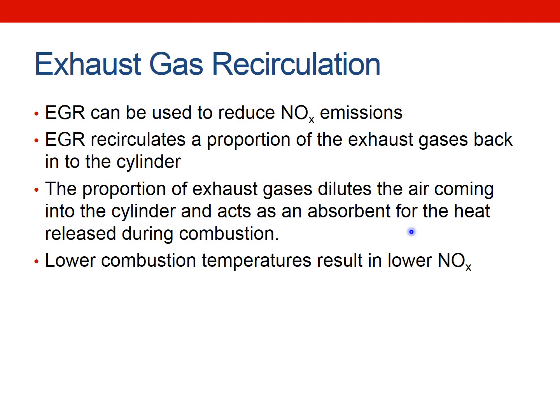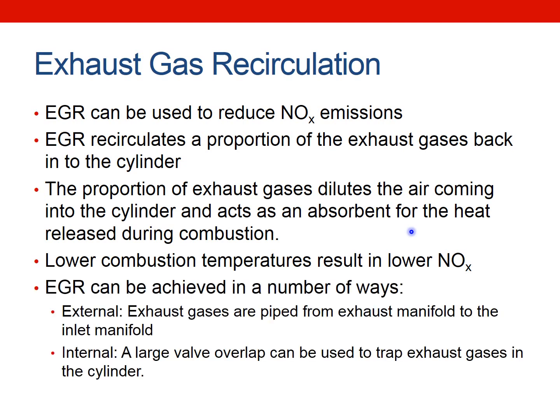And it's a lower temperature that gives lower NOx. And as I said, there's two ways it can be achieved: external, where the exhaust gases are piped from the exhaust manifold to the inlet, or internal, where there's large valve overlap to trap exhaust gases in the cylinder.